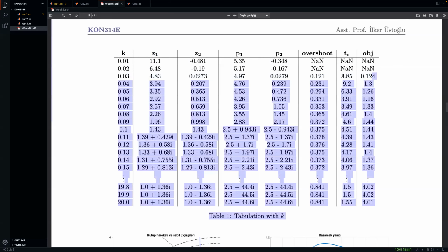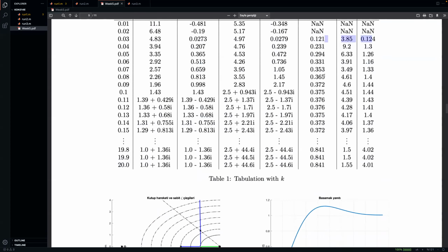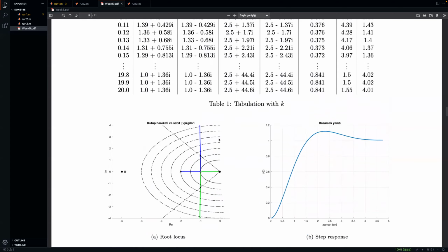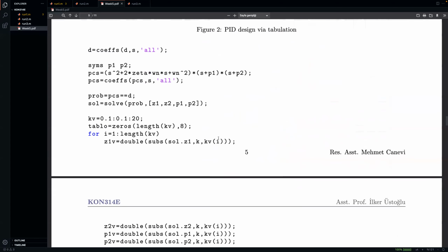Now you can see that probably this one is chosen as the solution that's being optimal, and you can see almost pole-zero cancellation at the origin, almost cancellation at -5, and we have this ideal thing. And you can see it's not really that important if the cancellation is exact, because it still works because it's out of the dominant region, and this is just not there at all, and it's not the system's pole that is going to be canceled.